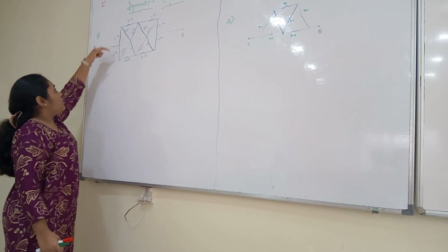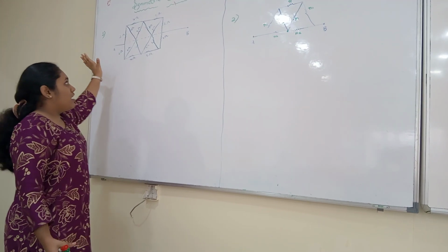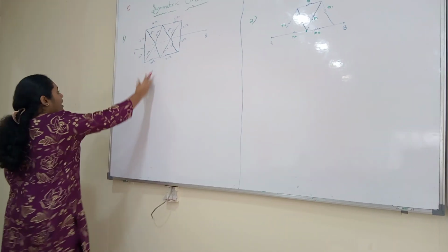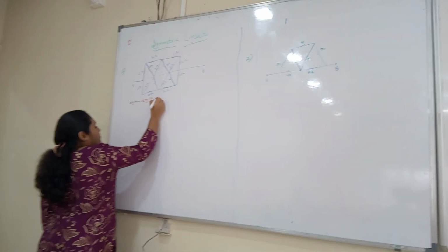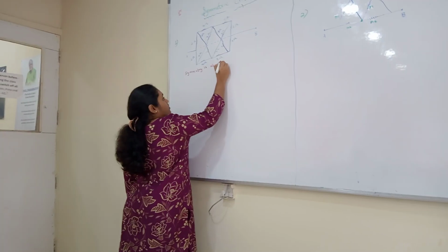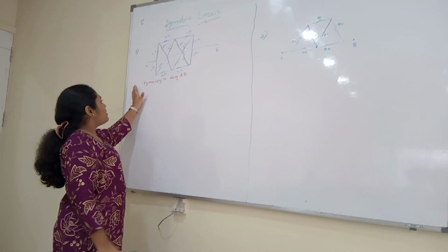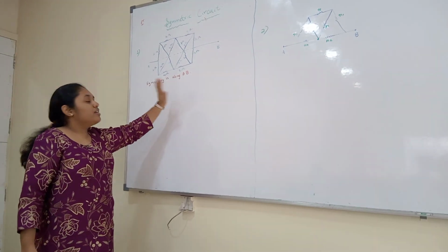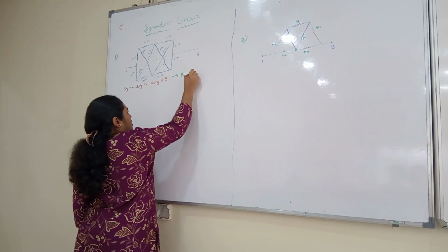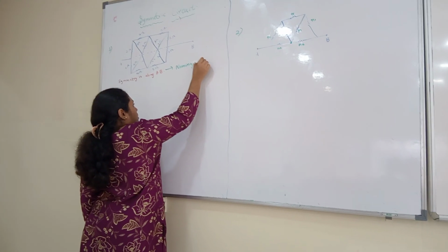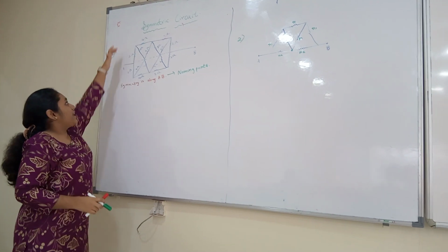You can see 2 ohm, 2 ohm, 4, 4. If you fold this, the same circuit is there. So the symmetry is along A and B. For this, the technique is naming points. We do naming points, but not such that AC is there and AD is not.